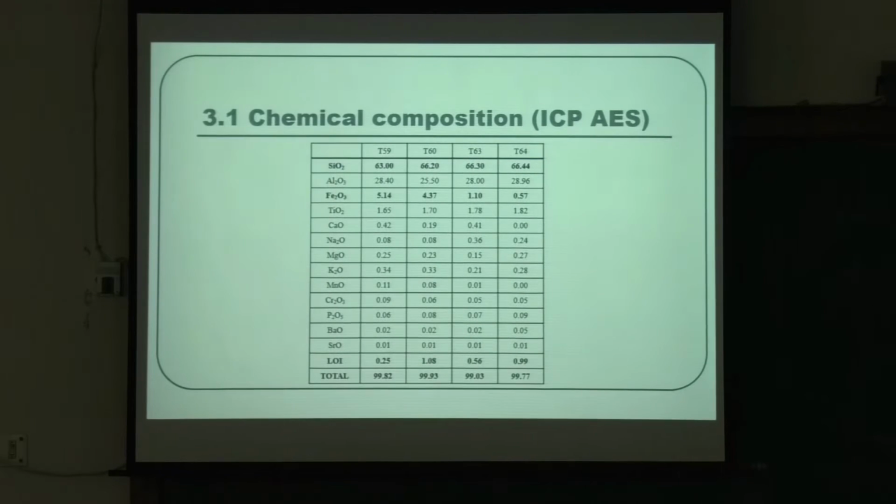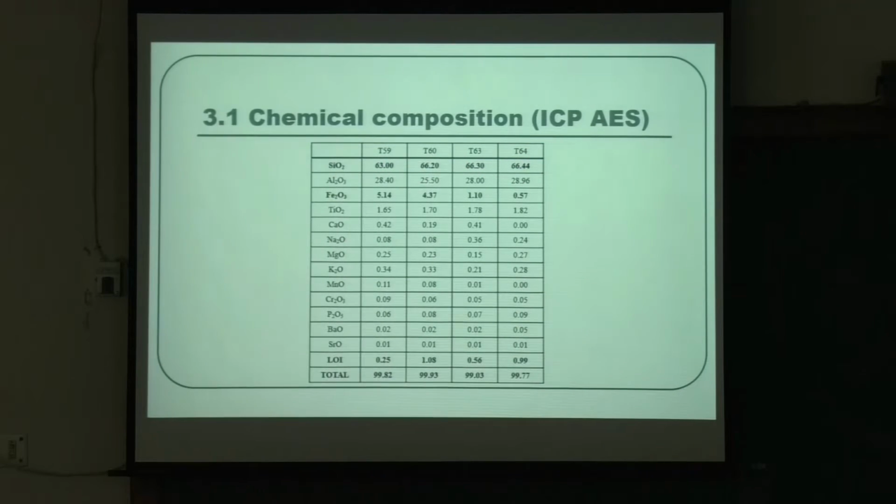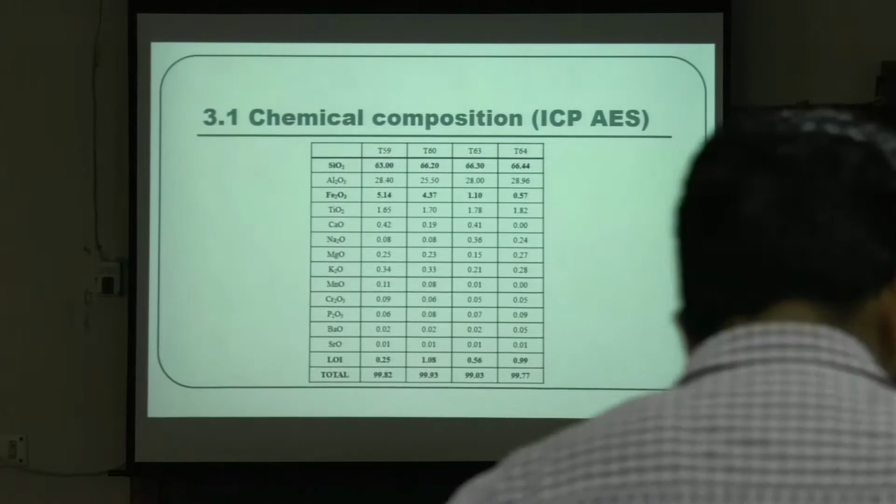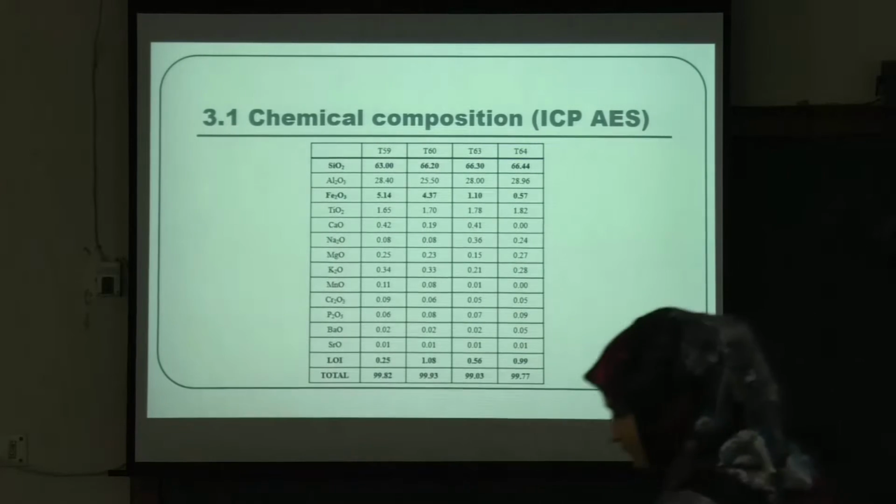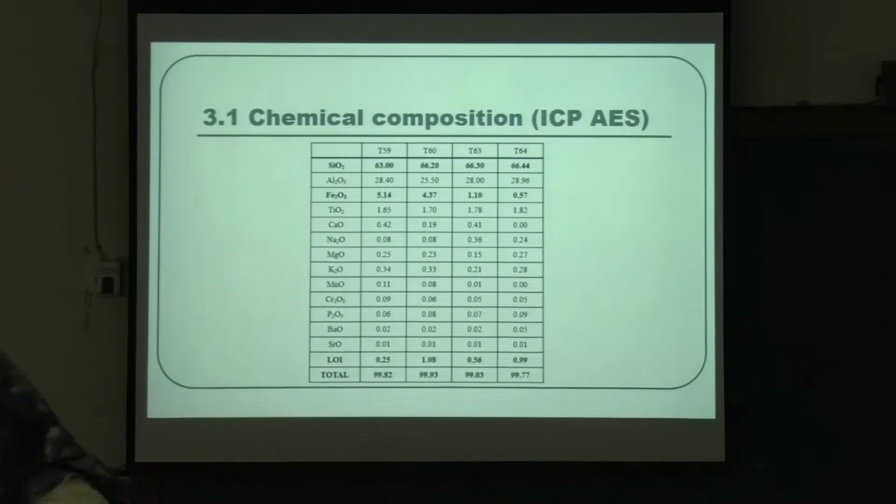And this is something which we have seen earlier, but it is worthwhile mentioning. All these 4 fly ashes have similar silica and also pretty low calcium oxide, so all of them are F-type fly ash. And then if you go to the LOI, the first one has the lowest LOI, and this is the middle, and the other 2 have quite similar LOI. So that is how the composition looks. So all 4 of them are type F fly ash because calcium oxide is very low.